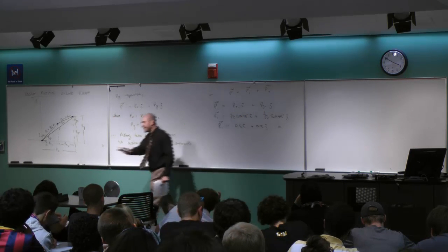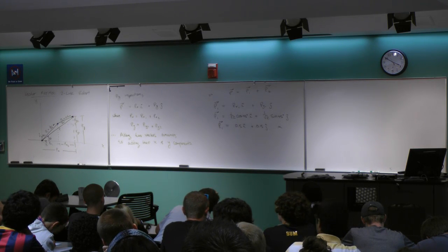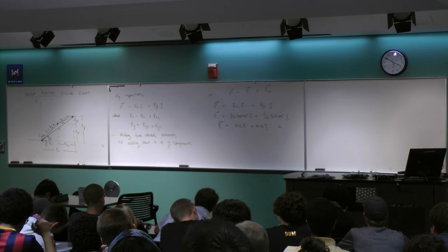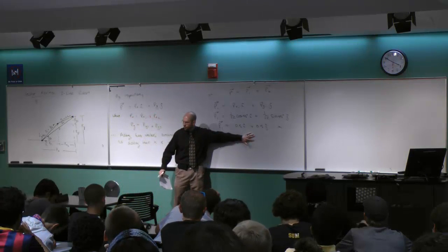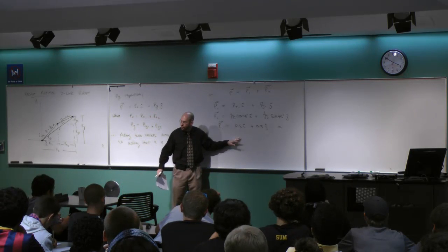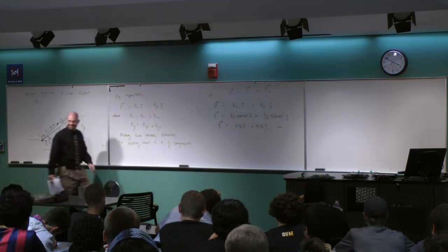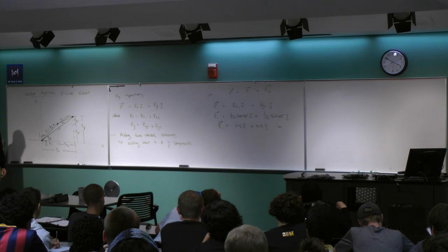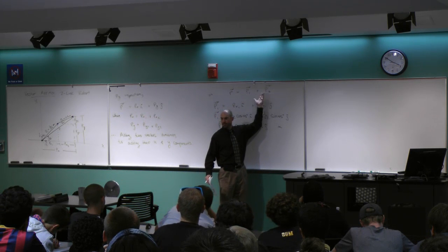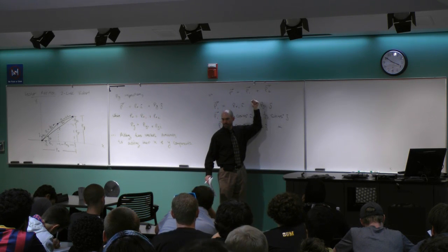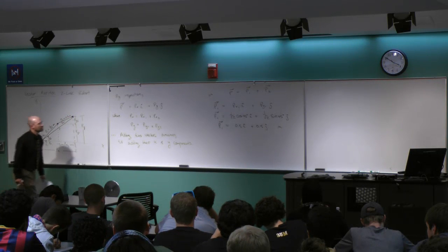Okay, so in any vector addition problem, task 1 is to write down the vectors in i and j notation. Any questions on how I arrived at this for P1? This is the position vector of the first link. You guys with me? Again, the goal is I want to write down P1 and P2, and I want to add them up. That'll get me my final P. All right, so we got P1. How about P2?